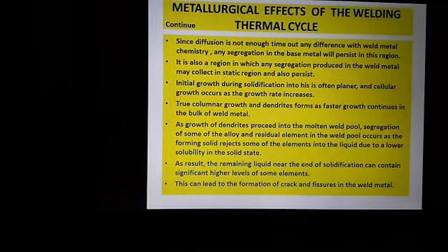Since diffusion time is not enough, any difference from the weld metal chemistry and segregation in the base metal will persist in this region.